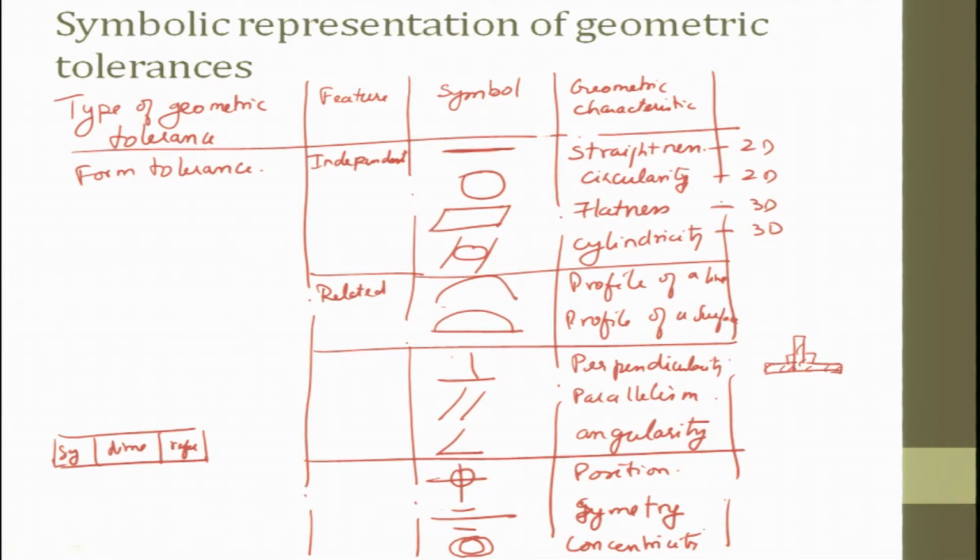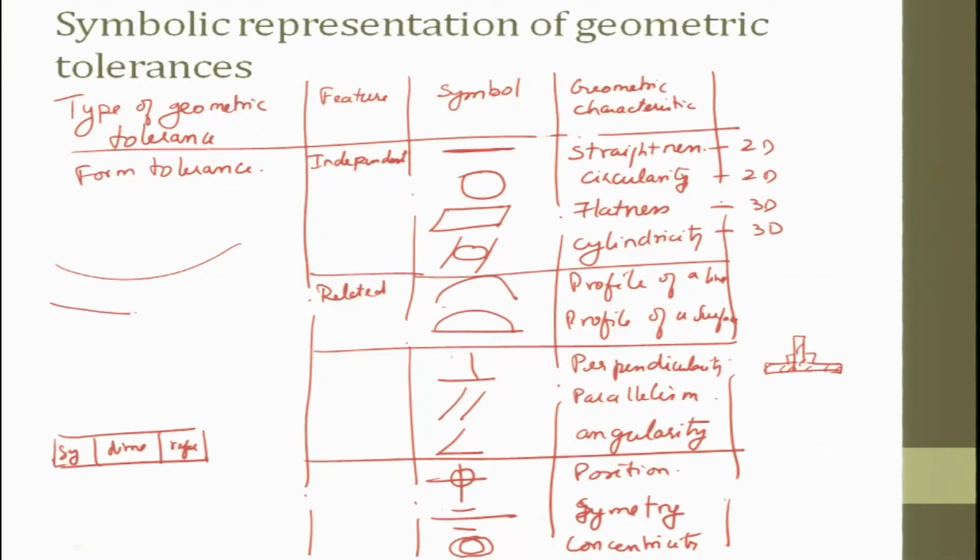For example, if I take a shaft and measure the diameter of the shaft, at every section plane you will see it falls under the dimensions, whatever it is. But if the shaft is something like this, all the dimensions you measured at several planes are perfect, but with respect to this axis it is gone.